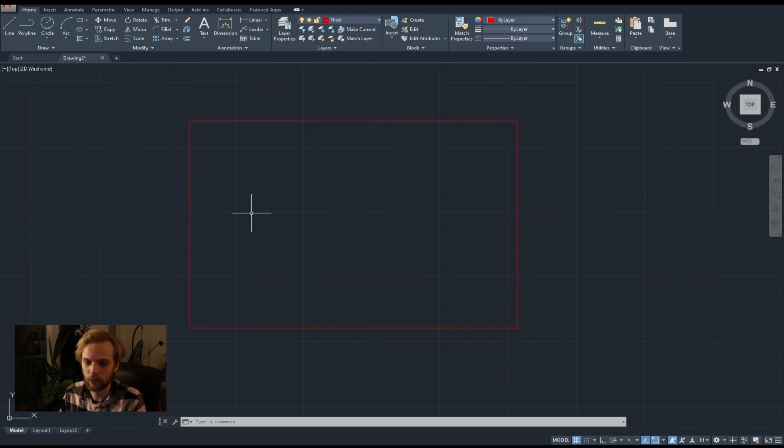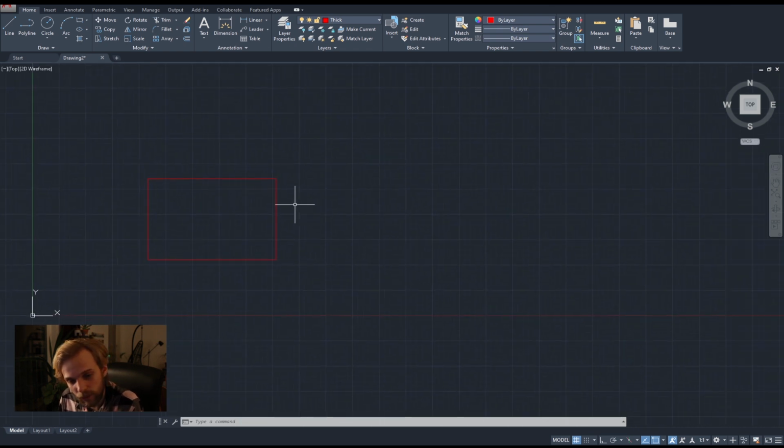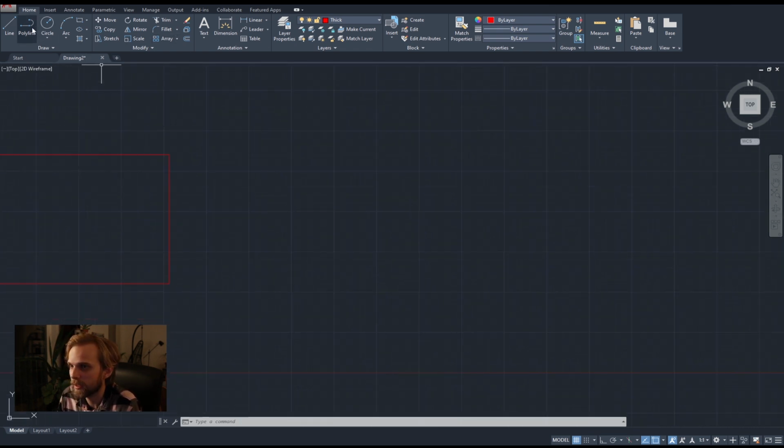So that's my outer footprint, right? My walls have thickness, of course, and for this I will say that the outer wall thickness is going to be around 400 millimeters. Usually they are a little bit thicker than that, but it's a summer house, it's a pretty small house, so 400 is okay. So what I want to do is make a copy of this rectangle inwards by 400 millimeters. And there's a tool that does that. I will show it on the side here real quickly.